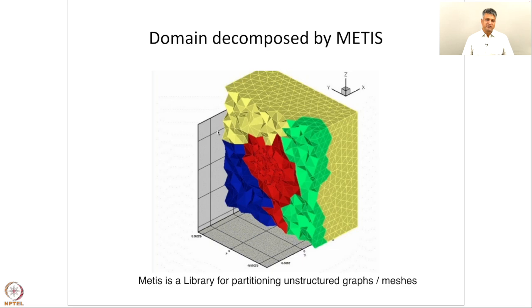The mesh also contains irregularly shaped tetrahedra. So you have many elements at the center where there is a small sphere which has been meshed, and as the mesh is taken away from the center of the sphere, it becomes coarser and coarser, giving more and more geometric spacing. From a computational perspective, it does not matter what the volume of this tetrahedron is or what the volume of the finest tetrahedron is. The computer just sees it as a singular point or a data point where some computation needs to be done. So the computational load of a large tetrahedron and a small tetrahedron is roughly the same.